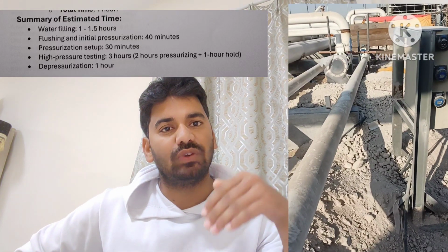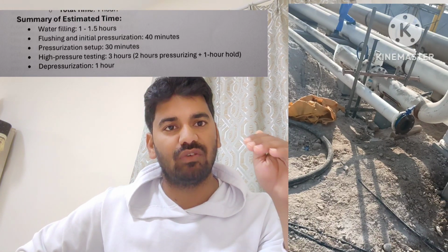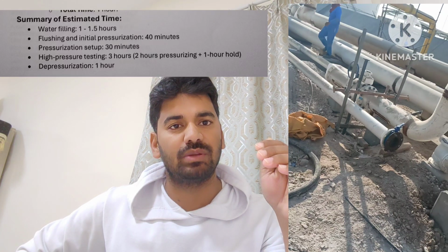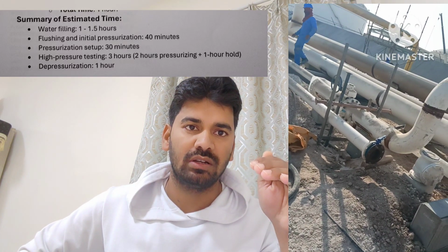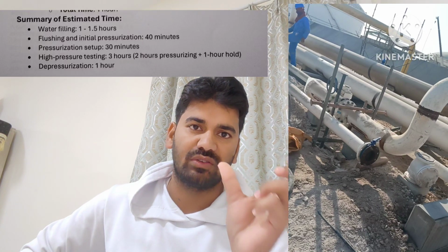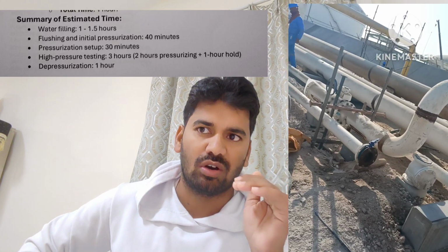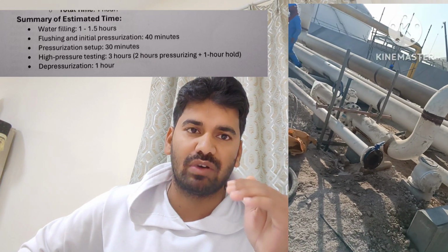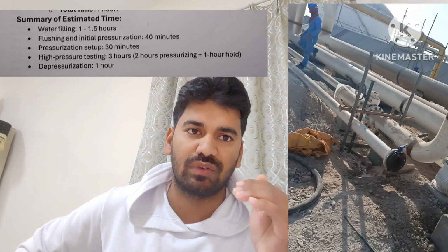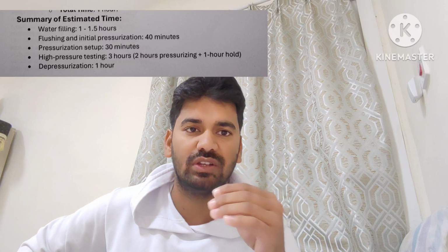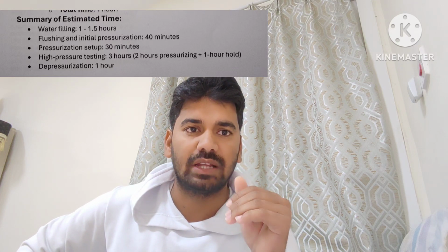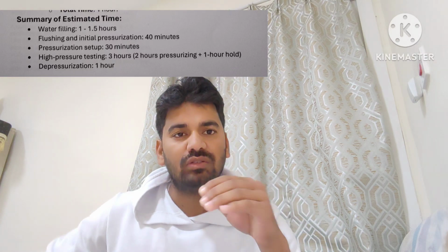Okay, that means you reach the maximum pressure of 150 bar, and when you reach 150 bar, you take 1 hour for the whole time. After holding completion, your pressure of 150 is still the same, maybe 151 or 151.2 because of temperature. It may increase because of daytime sunlight. When the temperature increases, the pressure also increases, so no worry.